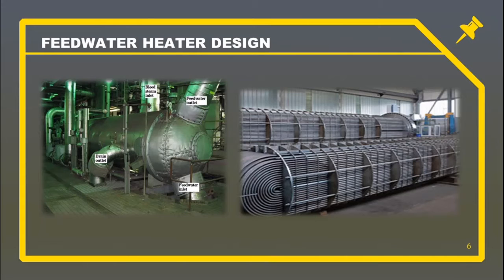In most configurations, the feedwater flows inside the tube side and the steam flows over the shell side. The tube materials are copper alloys and non-ferrous metals for the low and high pressure heater tubes. For low pressure heater tubes, copper alloys are extensively used.